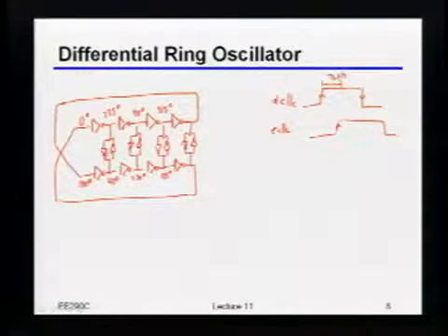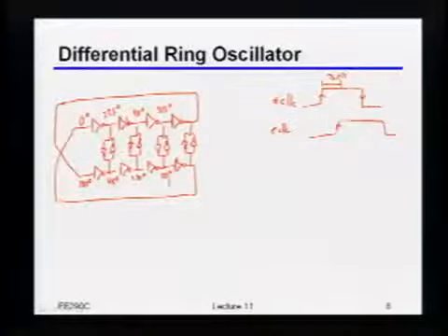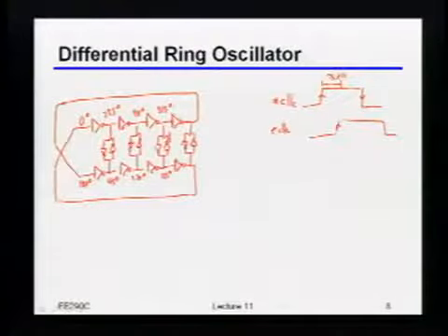You have more capacitance, right? This forces you to size things with a certain ratio, because if you don't, the whole thing may not work. So indeed, it slows you down. And remember, if I'm trying to do a 10, 20 gigabit per second link with a ring like this, I really want to push the frequency of that oscillator, because I want to get this thing to go just as fast as I can.